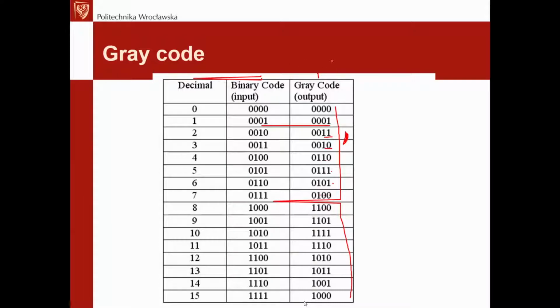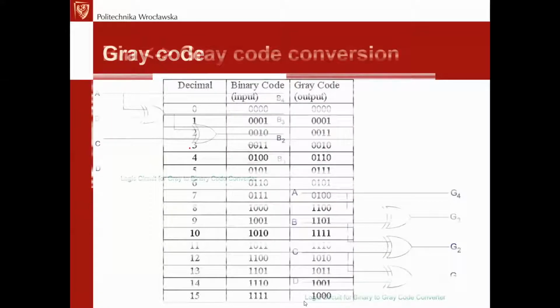The gray code is usually used as the output from various electromechanical devices, but microcontrollers very often need to be able to understand the gray input, and they often have specialized blocks for understanding the gray code.